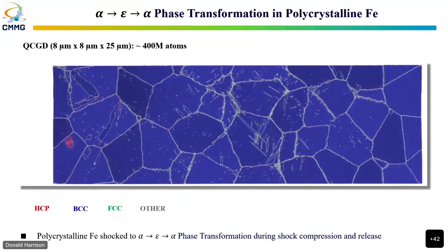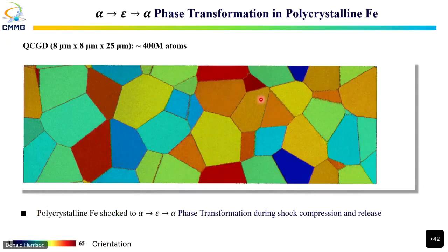The good news is now you start looking at these microstructures. There's a whole bunch of twins in the microstructure with grains that are randomly oriented. So first we thought that only the grains in the 1-1-0 orientation would twin, the other orientations would not. But now we are seeing twins in many of these grains over here. So that begs the question, is it orientation dependent, or is it also dependent on the misorientations with the neighboring grains? So we basically do the same texture analysis for this.